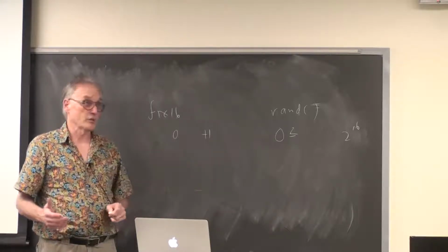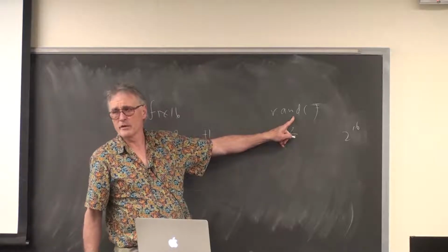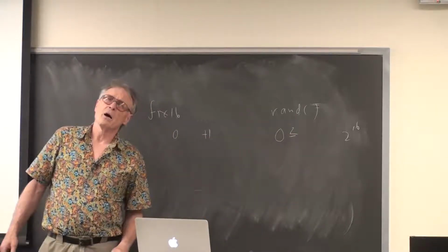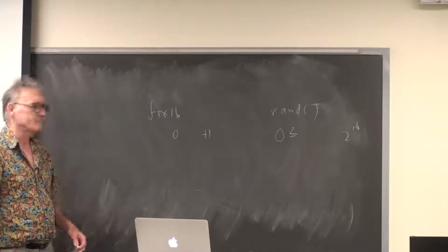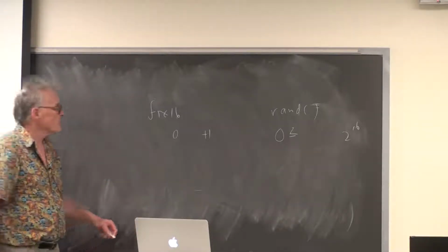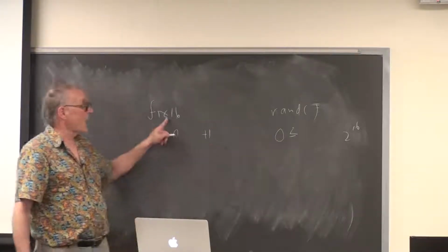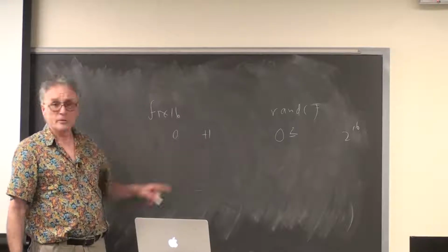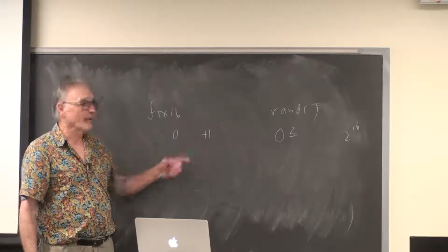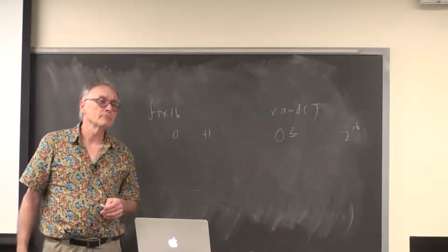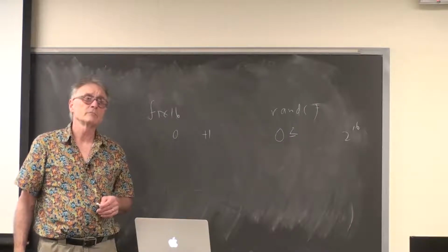That's pretty efficient. This is a fairly efficient random number generator. It uses what's called a linear congruential generator. It's 1 multiply, 1 add, and a truncation. So that's pretty fast. Copying it into a fixed 16 is very fast. Now you have a number between 0 and 1. You do that 10 times in a row, add them together, you have a Gaussian number to a very good approximation with a mean of 1/2.